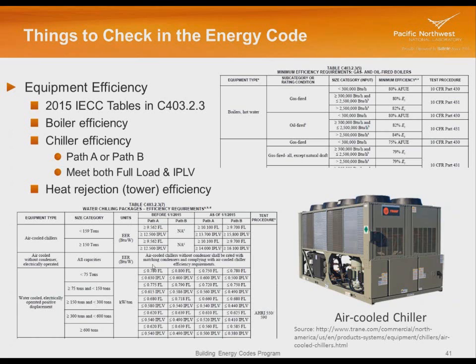On the chillers, same kind of deal. We have different types of chillers, air-cooled chillers separate from the condenser, water-cooled chillers. The air-cooled chillers are rated in EER, just like our packaged rooftop unit. And here's a picture of one. It's a lot like the packaged rooftop unit. We've got the condensers. We've got the compressors down in here.